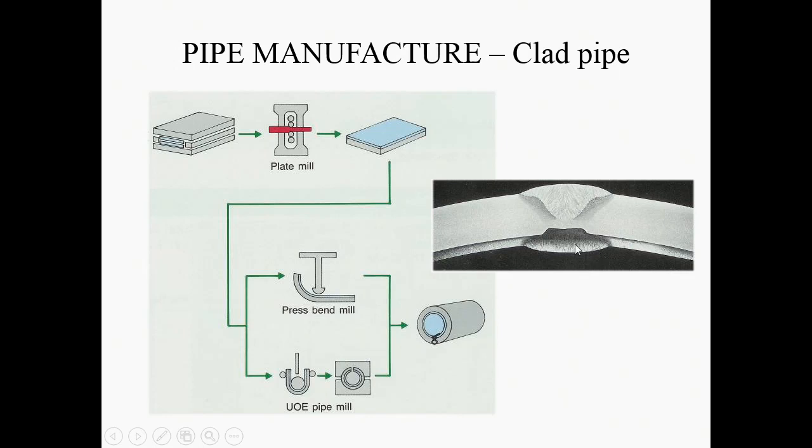You will get what's called dilution. Some of the carbon steel will migrate into that weld. So maybe its corrosion resistance isn't good, and you'd have to therefore choose your welding process in order to maximise the corrosion resistance that we've got.